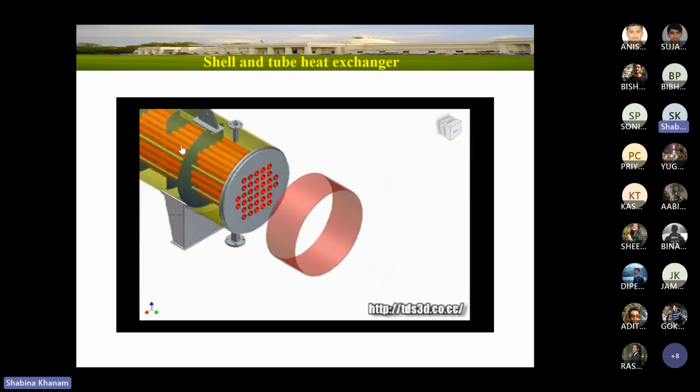Now once I have the other tube sheet, this is the complete shell. If you observe the space between two tubes in the shell, that space is sometimes less than the opening in the tubes. Though we understand that the shell diameter is very high, the space for movement of the fluid between the tubes is quite small in comparison to the tube ID. I hope you are getting my point.